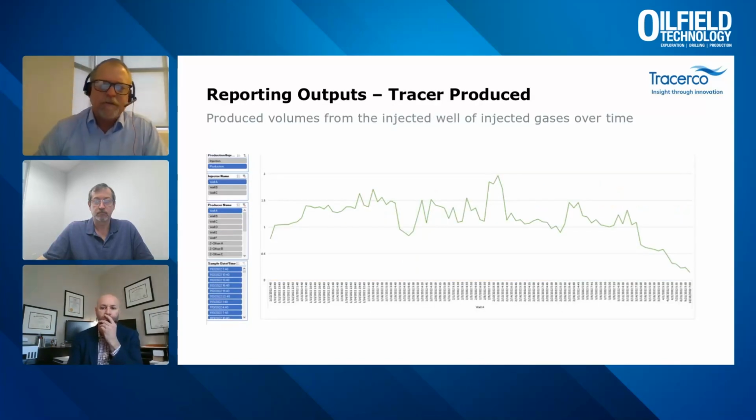After the injection cycle, during a huff and puff or surfactant injection cycle, the wells are put back on production. So now we're looking at the tracers that were applied to one of those 3 injection wells and being produced from that well. With the concentration produced and also the known volumes being produced, we can work out the masses of recovery and percentages of recovery from the injection gas.